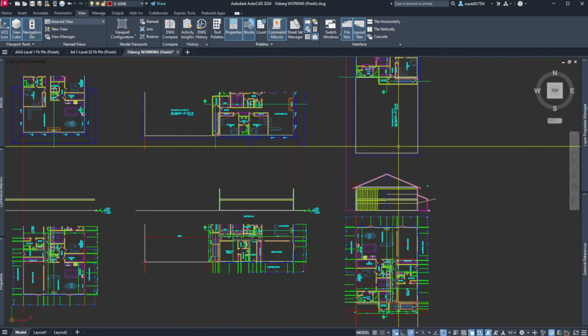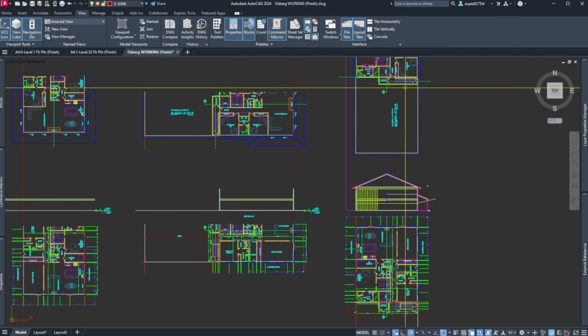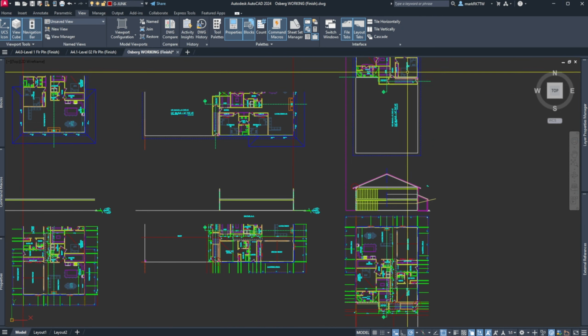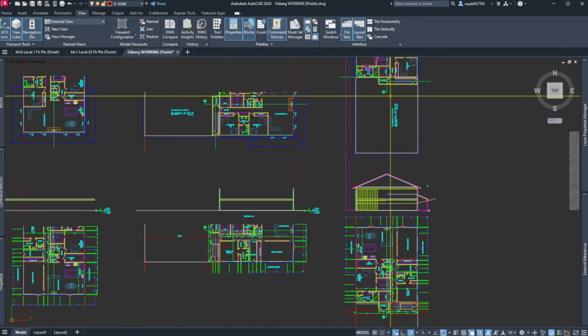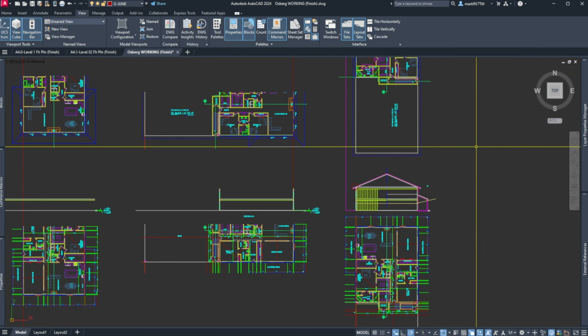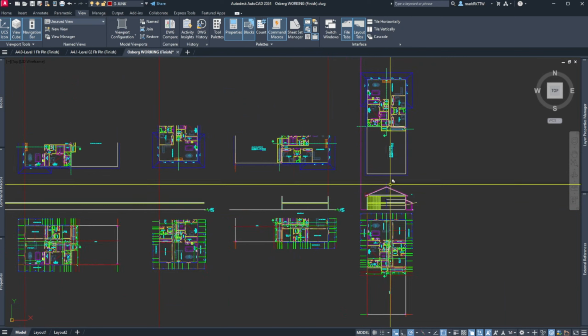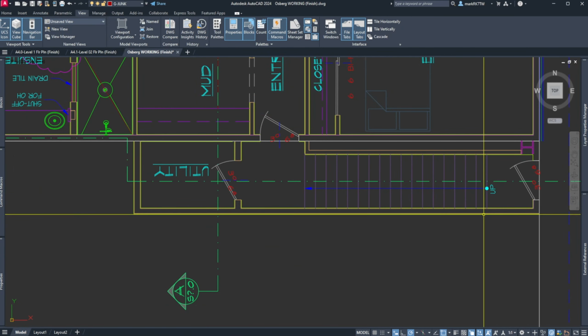Now, if we wanted to do interiorly, I'm not afraid of a 10-inch tread. Sometimes people do 11 and a quarter because that's a standard 2x12. But if you're going to do any sort of finish work, you're going to lose some of that. So I usually don't do that exactly.